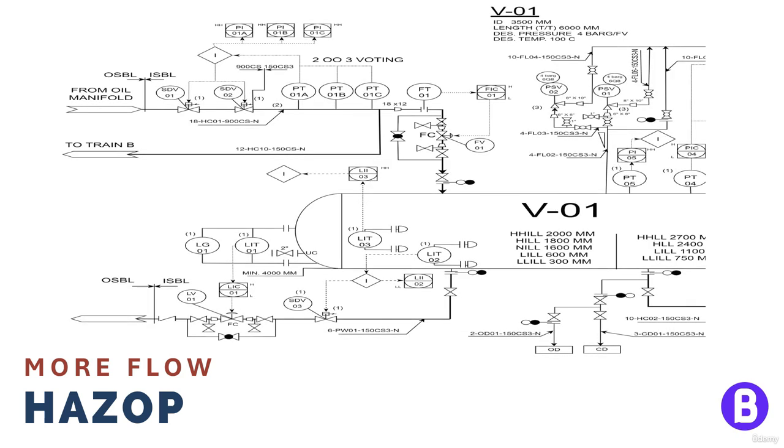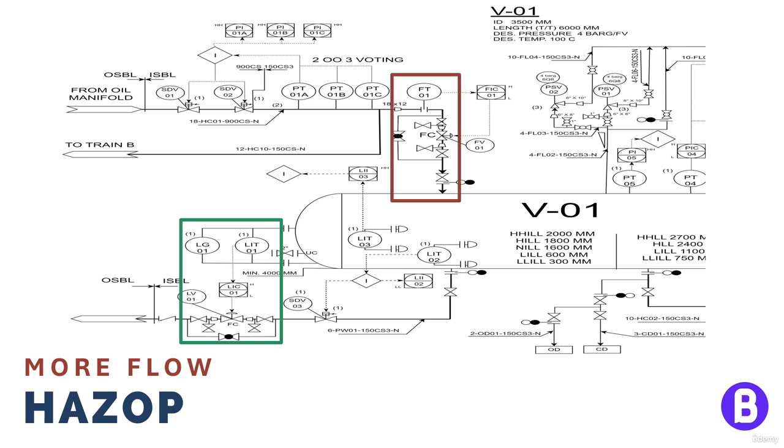So, if we have a level rise in the vessel due to high flow, this is commonly checked in the deviation related to the high level. As we see, there is a level control in the water line. This shall adjust the flow during normal operation. But could it be considered as a safeguard? Well, if the failure in the inlet flow was just related to the flow control loop, then the level control loop should ensure that the level is still in an allowable region, which can be considered as a safeguard in this case.